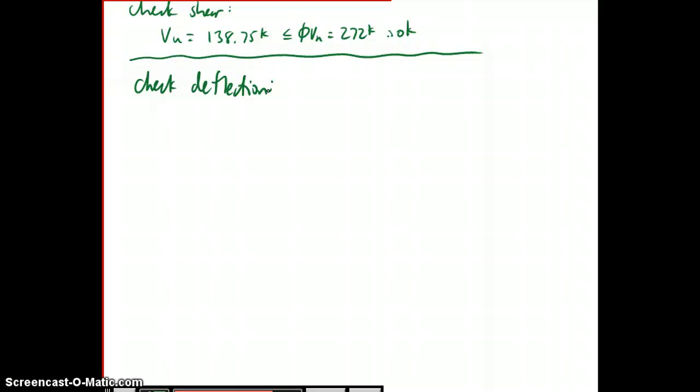If we were to kind of peanut butter spread that 210 kips across the whole beam, we would have a w sub u of 8.75 kips per foot. So we'll assume that for starters. And when we back off by 1.6 for the live load factor, then we have w sub L equal to 5.47 kips per foot.